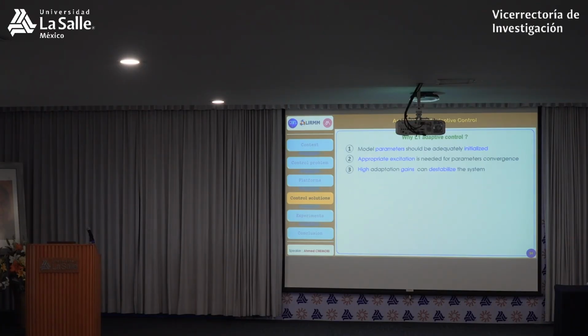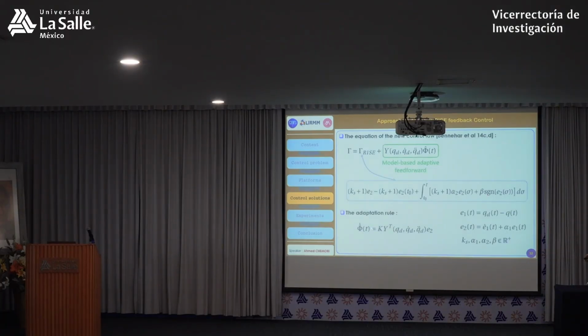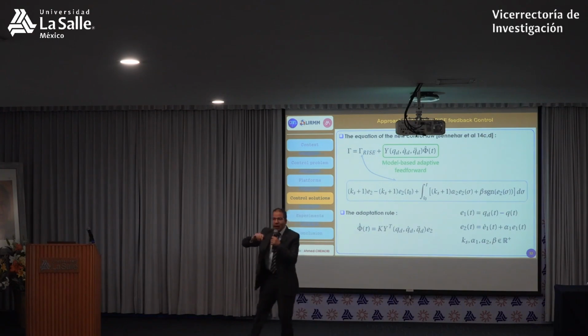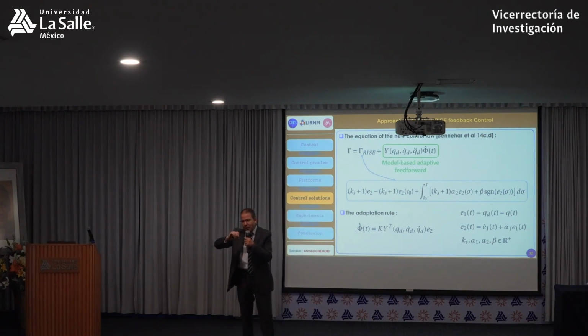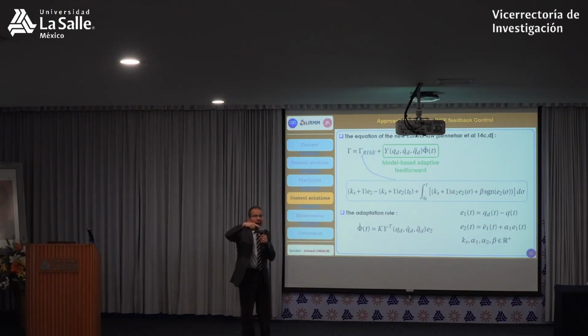And third issue, when you are estimating the parameters, look at this law. You have here K, what we call the adaptation gain. The best way is to converge quickly. The real value is here, you are here. If you converge slowly, it does not work because in the meantime you are not using a good gain and there is error until you converge. To converge quickly, you have to increase K. However, if you increase K enough, you may have oscillations.